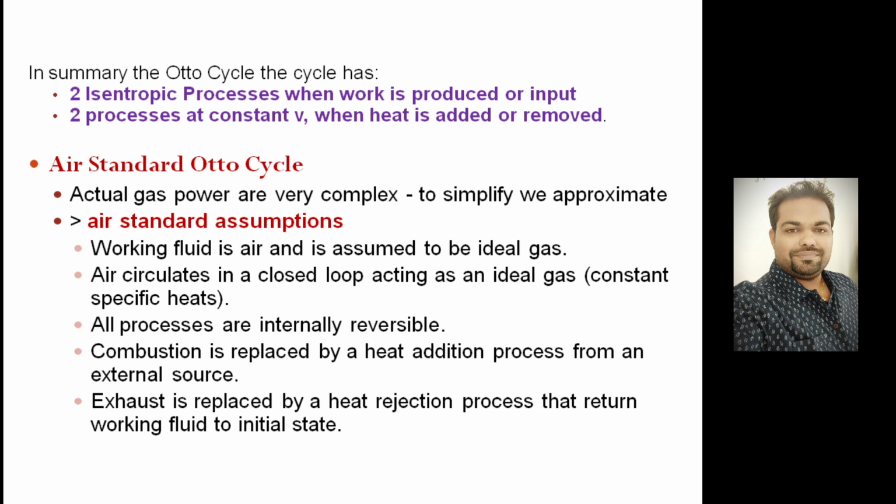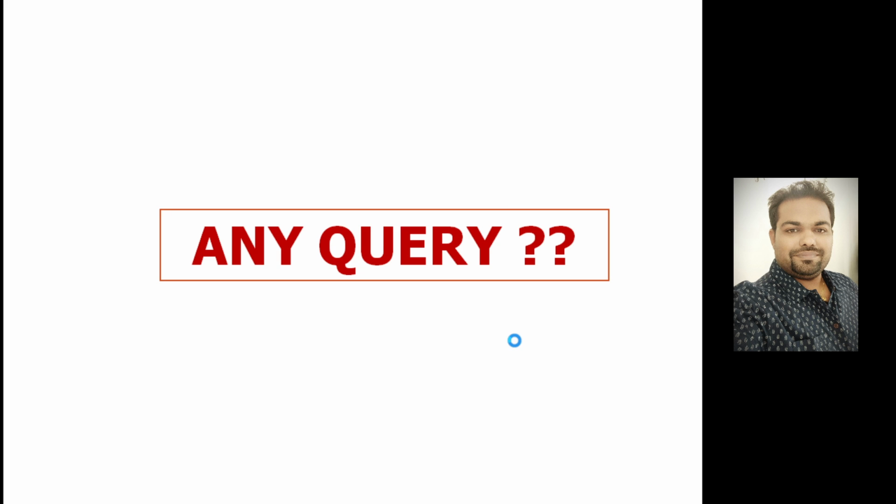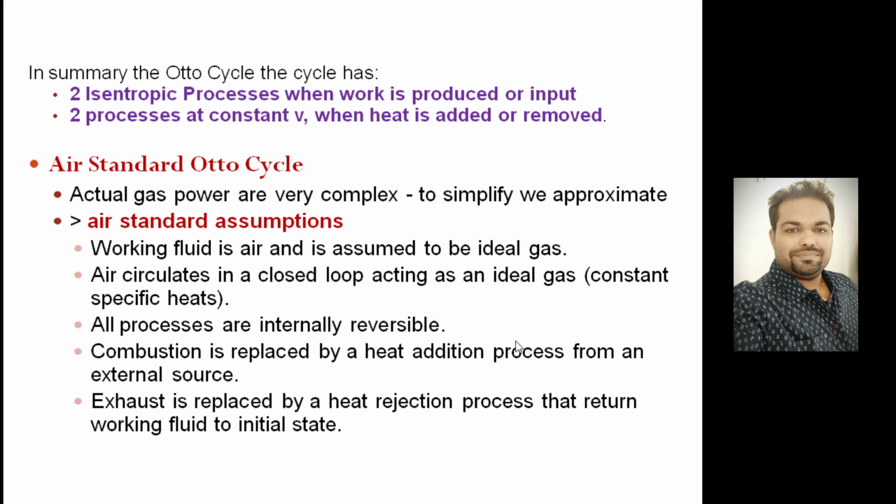So instead of doing so, we are making this an idealized cycle where air is the working fluid, air is continuously circulating in this circuit and producing the mechanical work, and we are not adding any fuel in this. So this is basically the air standard cycle assumption, right?